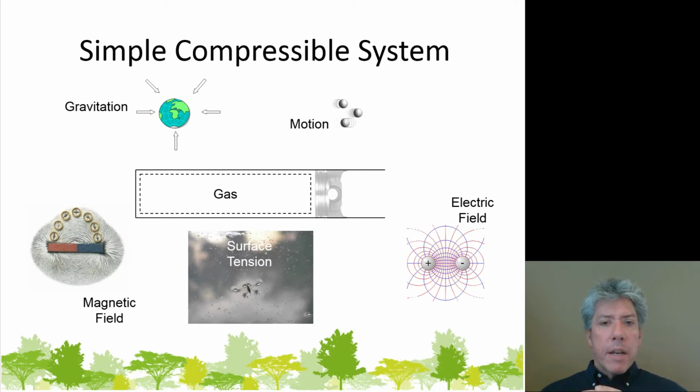So think about it. Well, the gases there are certainly moving faster than the bullet. They're what pushed the bullet out so fast in the first place, right? In the same way, the gases on the molecular level in the piston cylinder device are moving a lot faster than the piston, and so motion is something that we can neglect.